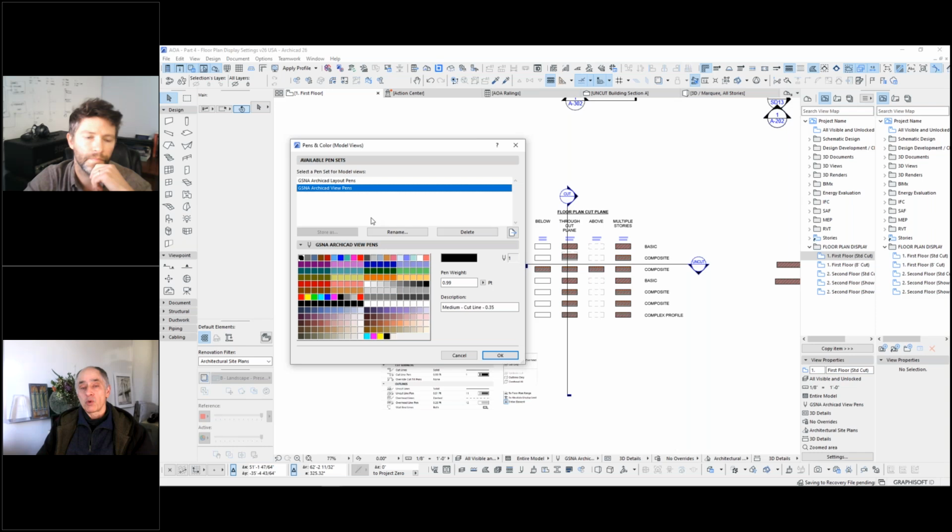And if you were to copy and paste stuff, it would come in. Layers, I believe the layer naming conventions were a little bit, well, certainly when I started the template, there was a lot of legacy stuff based on the National CAD standards limited layer naming length. And so by creating longer names that were more explanatory, it became more intuitive.